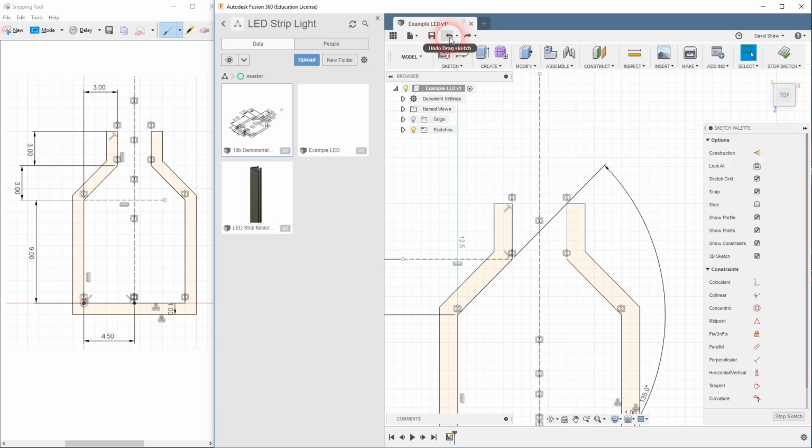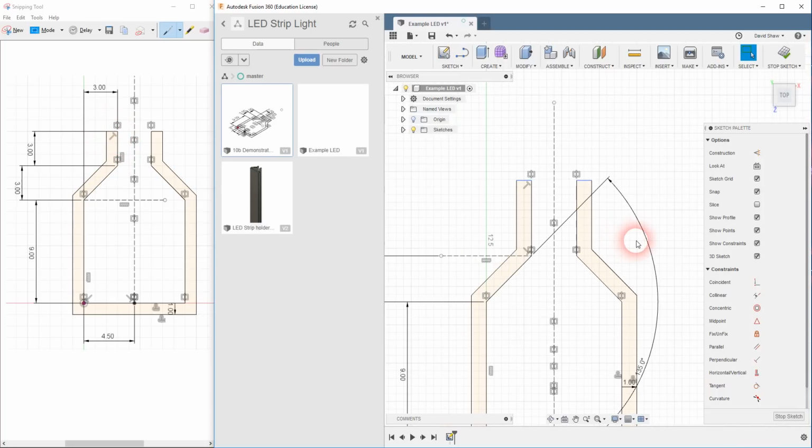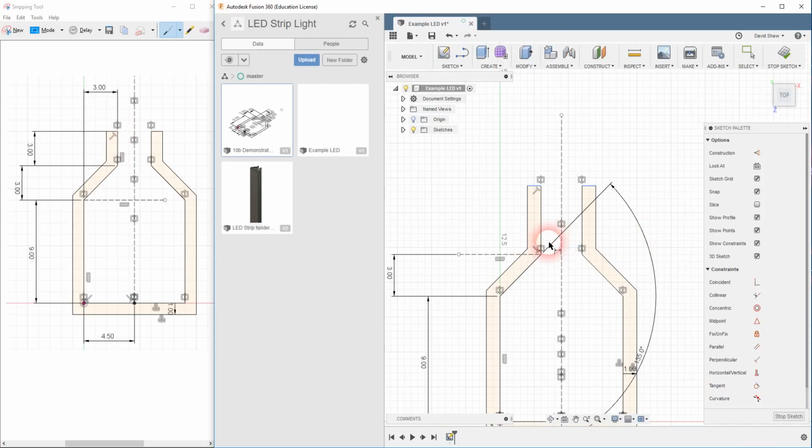I'm going to undo that, and I'm going to undo it back to where I was. But no, I'll leave it like this. What's missing here basically is this dimension line here. Now notice that I'm going from this internal edge here to the top, not from the external edge. So let's just zoom out a little bit here, press D for dimension line, and I want to just define that. Let's see the distance. Let's see, am I going to have to record that distance? Let's have a look. Record that to 3. Yeah, and there you go.